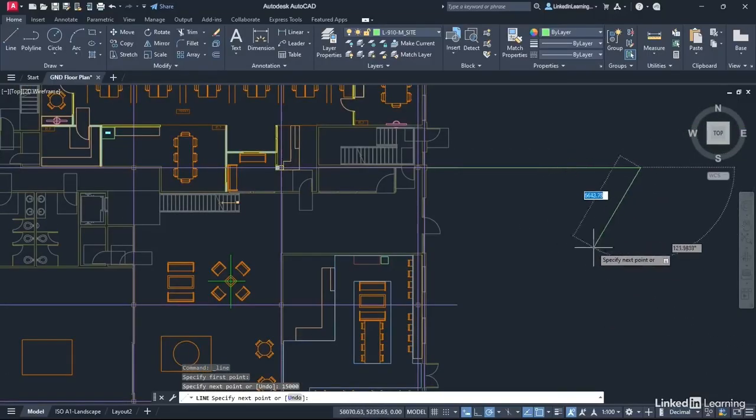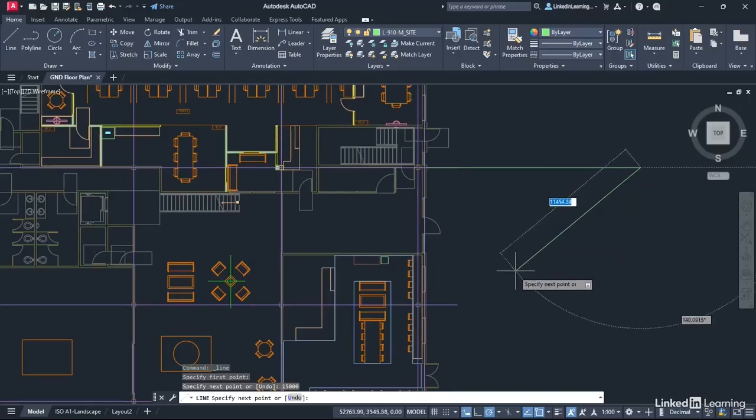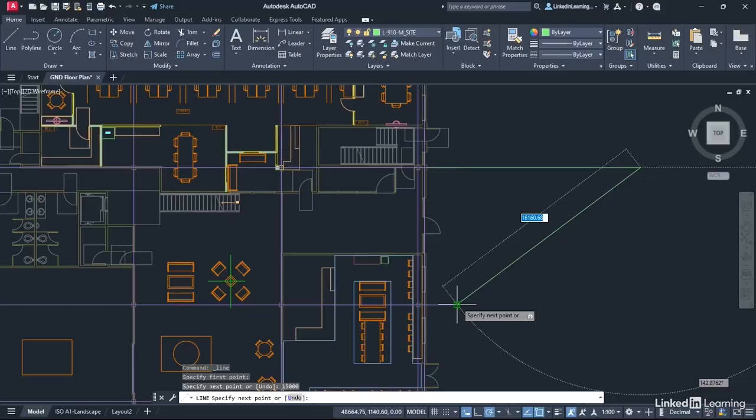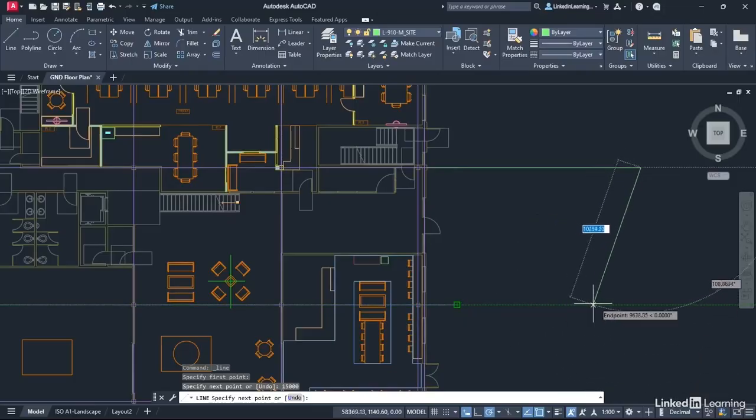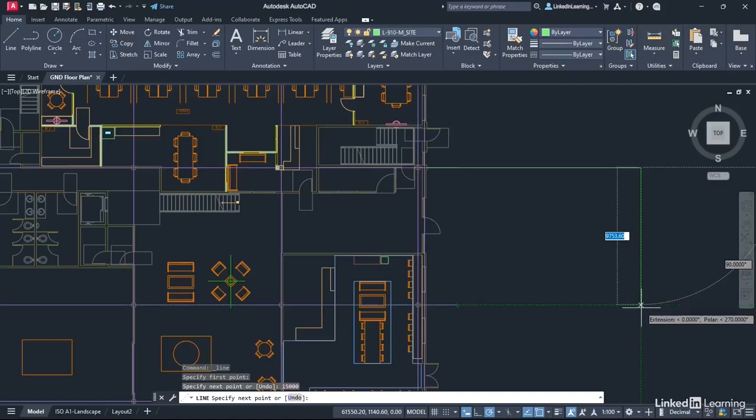There it is there. Now, we're going to utilize a little trick with our object snap tracking. We're going to hover over this end of the grid here, like so. Don't click on it. And then just drag along. And as you get to the vertical there, can you see you get an intersection? So that's the intersection of the end of the line that you've just drawn and the intersection of the grid line. Left click. That's a nice vertical line.